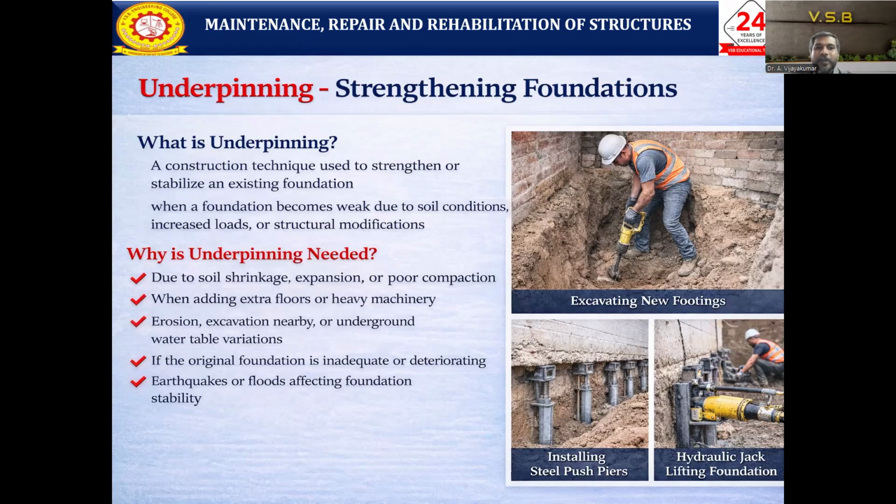When a foundation becomes weak due to the soil condition, or maybe a loading condition or a structural modification condition, our foundation starts to lose strength. For that, we cannot demolish the entire structure. Instead, we can go for the underpinning method to strengthen the foundation.